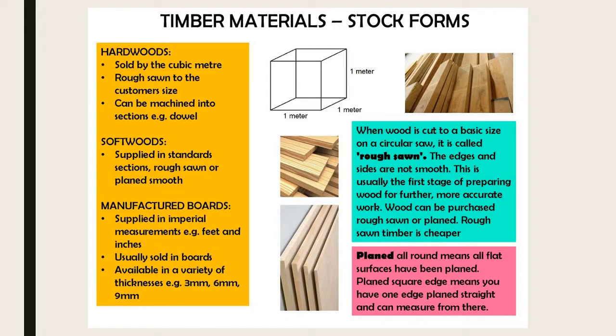So typically, if you're going to get some natural timber, but you need to cover quite a wide surface area, you're going to have to join the material together. Now, typically that will be done through biscuit jointing, where you cut a little groove with a biscuit saw, and then you put material inside it, glue it, clamp it that way, which looks nice, but is a natural weakness because it's a join. Whereas typically in things like construction where plywood's used quite a lot, you know it's one solid piece, it's the size that you need it, it's a lot more convenient that way.